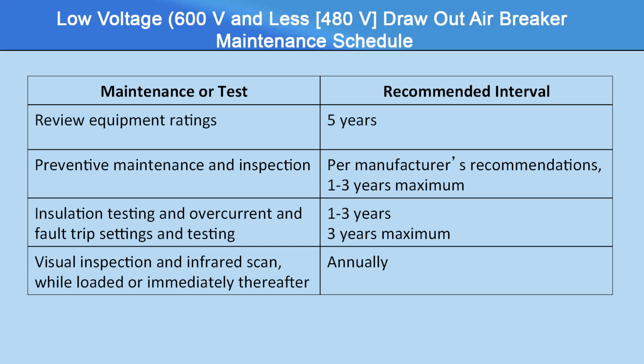High voltage circuit breakers are located in separate breaker enclosures either indoors or outdoors. These are oil, air blast or SF6 breakers. Examples are 115 kV and 230 kV breakers located in the switchyard.